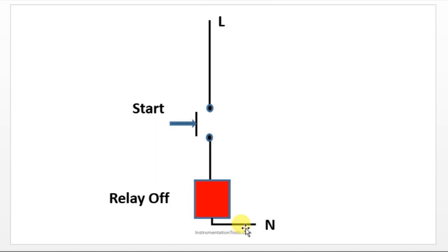If this is the working of a push button, why, in all automation industries, are people using push buttons? Most of the input devices, as a switch, people use push buttons only. So there should be a logic to make the output remain in the on condition. How can we press the push button all the time to keep the output on? There should be some concept, which is called latching. If you press the input and even though you release it, the output stays in the on condition. This is called latching.